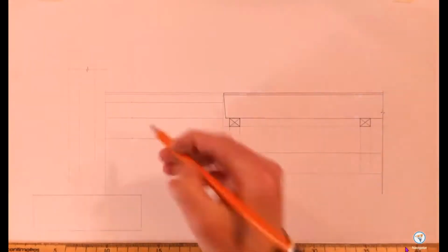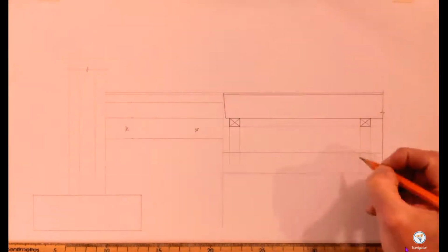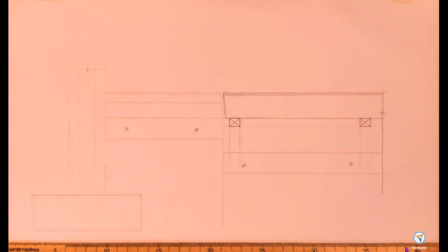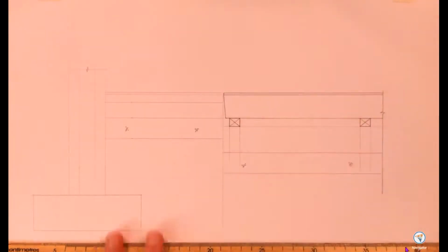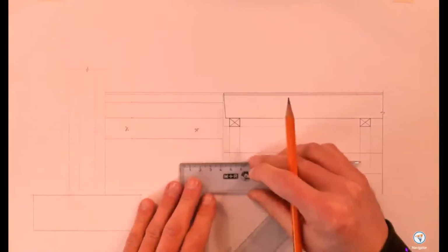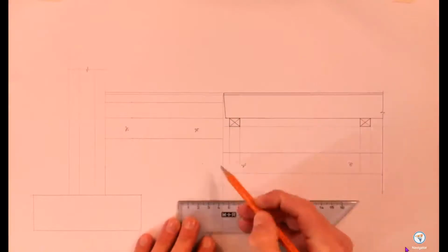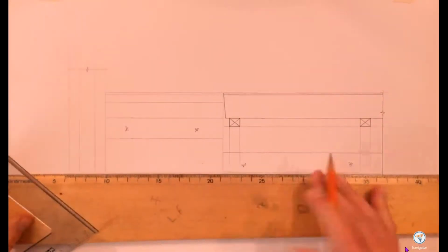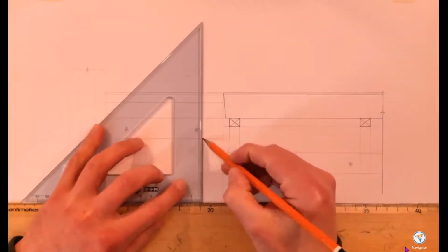Now I've got my subfloor here in the first part of the drawing, and subfloor here in the second part of the drawing, and we need to connect those two together. So we're basically just going to draw a line to join the two together. We need to maintain the thickness, so I'm going to come back here 20 millimeters. So I'm measuring out 20 here, and it's just going to help me maintain the thickness. So this will be one solid floor when I draw it in.